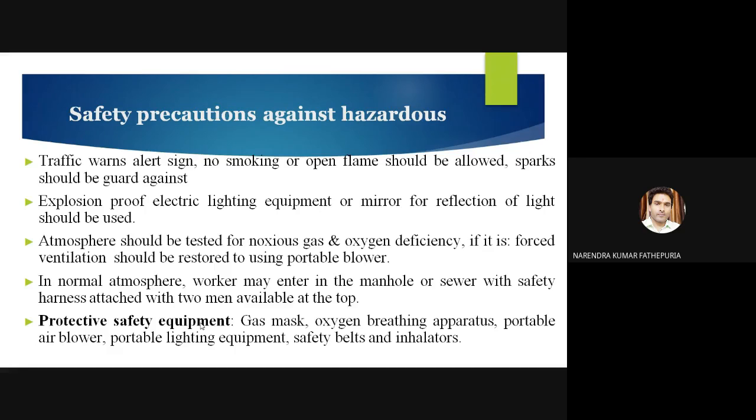Anyway, if a person is required to go inside, then what protective instruments does he have to carry? How many persons are required for it? All these things. Wherever you want to repair the sewer pipeline, you have to block the road for the particular dimensions. You have to clearly provide traffic warning and alert signals.